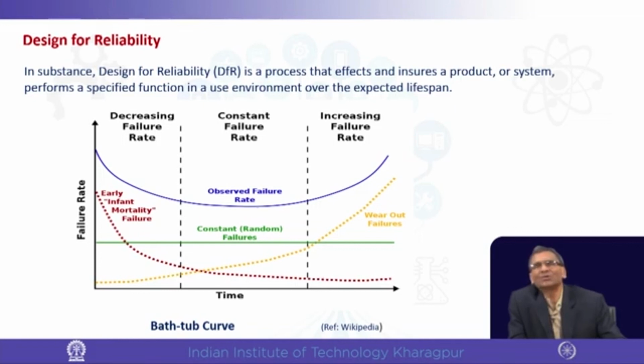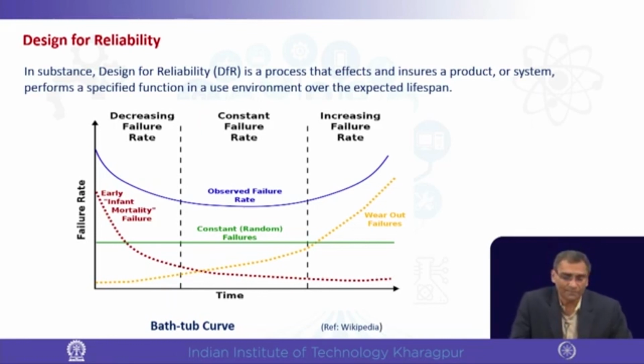And it leads us to the last leg of today's discussion, design for reliability. So, what is design for reliability? Perhaps you have read about it earlier also, but I will explain the bathtub curve. On the y axis you will find the failure rate, and the x axis is time. Initially there would be multiple failures, because of what are called teething problems. When you are planning something new, launching something new, doing some new prototype, there are many snags which will fail. So, in the red line we will find that initially there will be some failure and it will become steady.